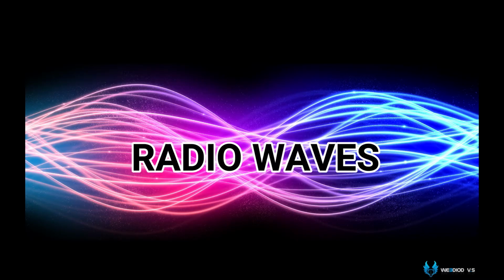There are three types of wireless transmission waves: radio wave, microwave, and infrared. Radio waves use omnidirectional antennas, with frequencies between 3 kHz and 1 GHz. They are used for multicast communication such as radio and television, and also paging systems. Radio waves can penetrate buildings easily, so they are widely used for indoor and outdoor communication.